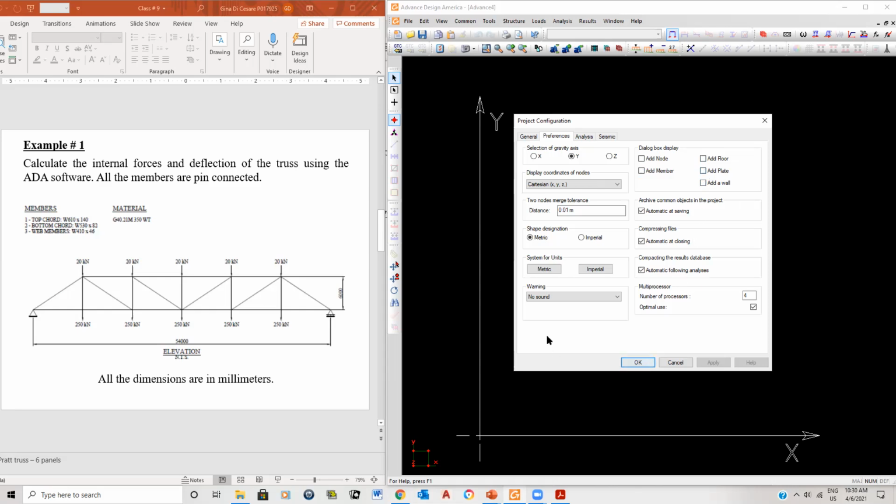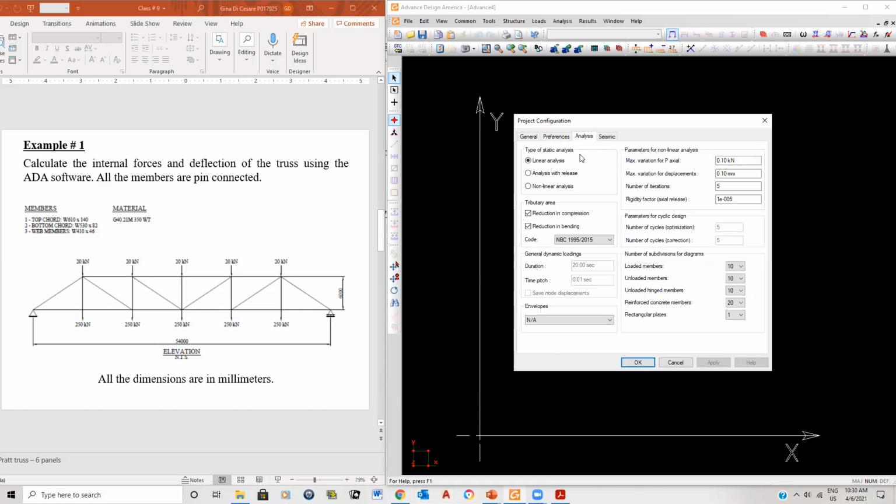or do something. As far as the analysis goes, if you ever want to get 20 results per member, or 100 results, this is where you change them. I don't bother with that. As a matter of fact, for trusses, I'd like to bring this down to 2 results, but I'm going to leave it at 10 for now. It doesn't make a difference. So everything's good here.